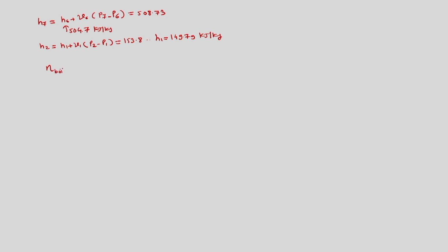So boiler efficiency is given as 88%, which is basically Q in divided by mass flow rate of fuel into its calorific value. Basically we have to find out Q in over here. Q in is basically m dot minus m dot b, which is the mass of the steam, getting heated from 2 to 3, and then only m dot b gets heated from 7 to 3.